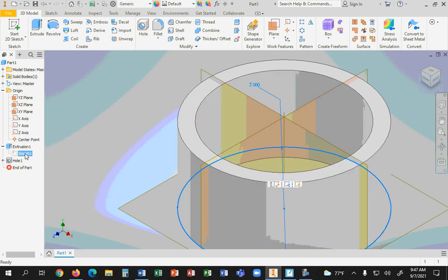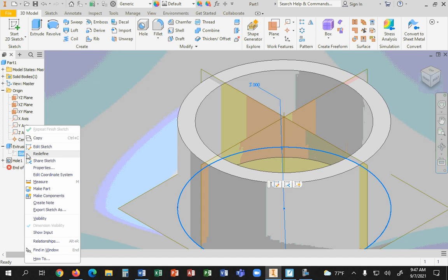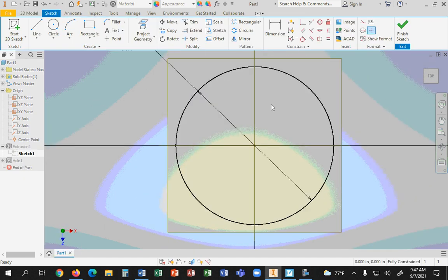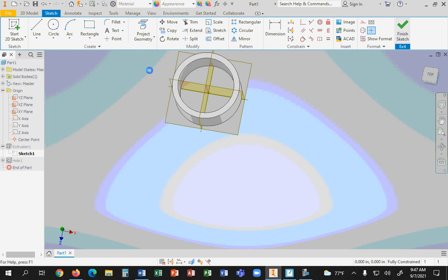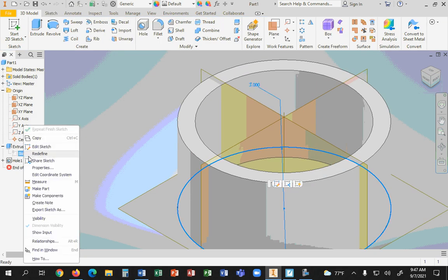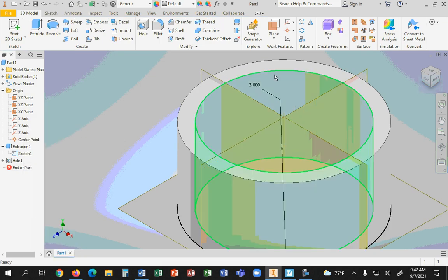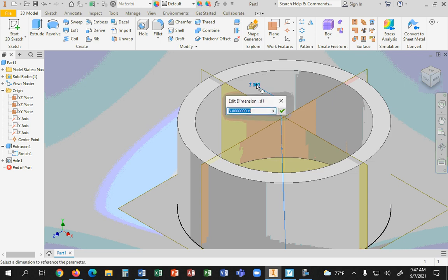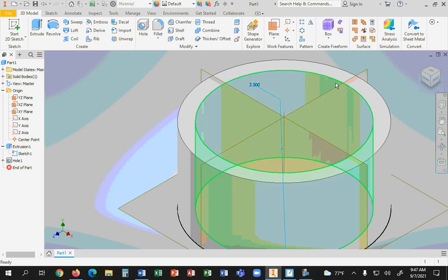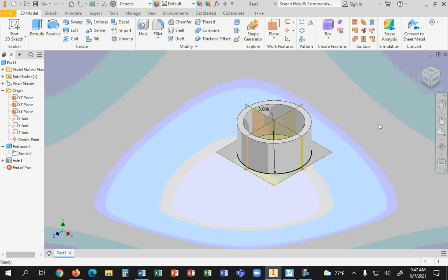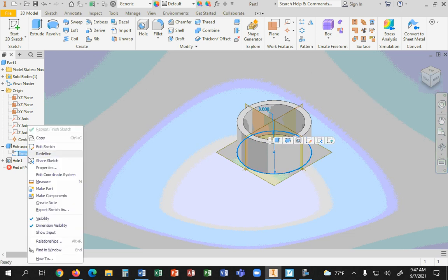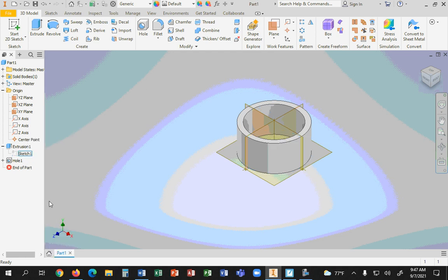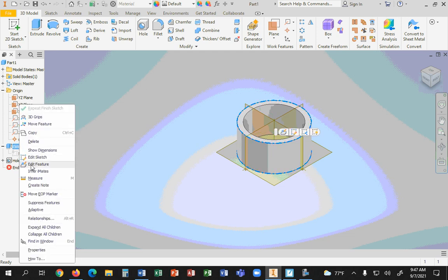So if I want to edit that sketch, I have to click on that, change it here, finish it. I can turn that sketch on, make it visible, and then I can manipulate it on the fly. See that? But having all your sketches on is a visual nightmare, so I tend not to. Got it? When did I turn a sketch on last time? What was I doing to it? I was sharing it. Remember that? That was in the first example I gave you guys. That's when I was sharing the sketch. So I had to turn it on so I could share it.